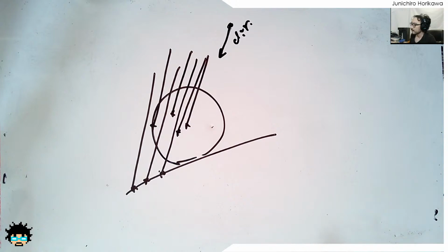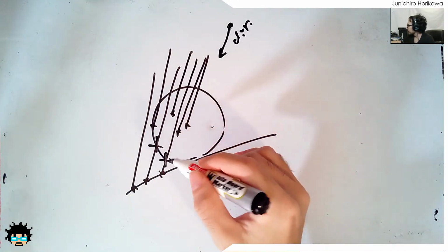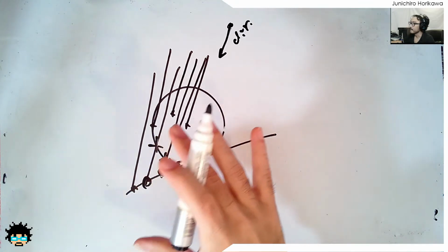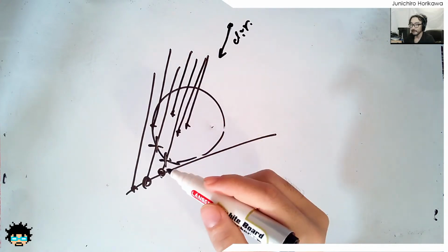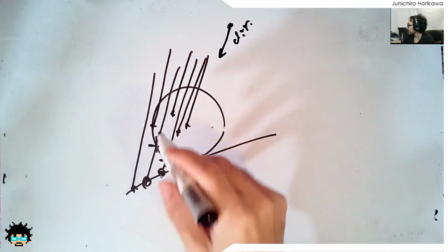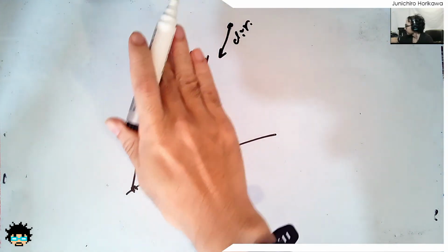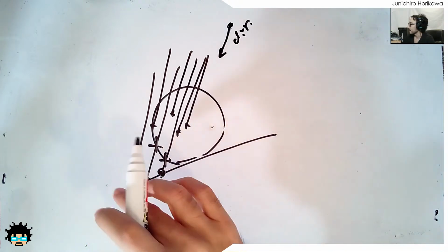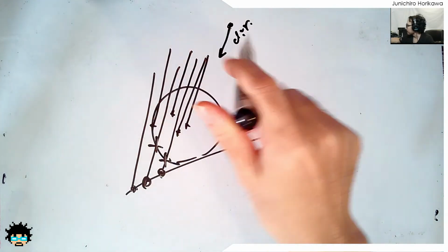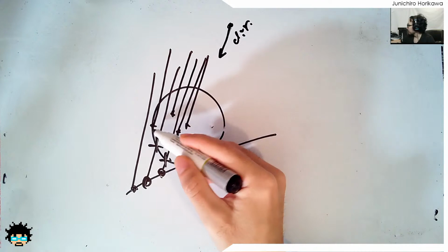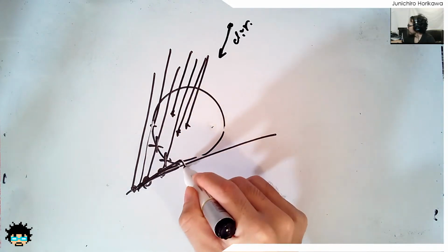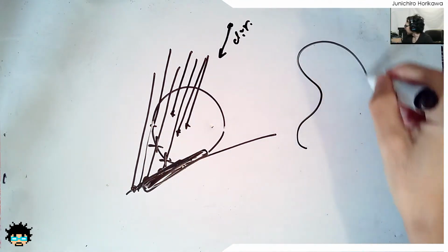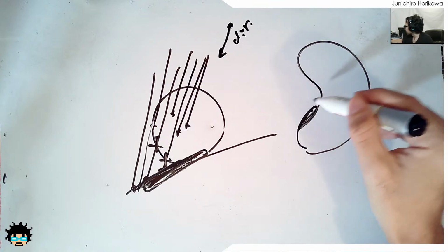And then as soon as you find any intersections on other geometries from this point, then that means this point should be covered by a shadow, right? But this one is not covered by a geometry. It doesn't hit with any geometry, so this doesn't have any hit. So that means it is not covered by a shadow. You can see through with this sun direction. So by doing it, you'll be able to define these places on the floor as shadows, and if you have a self-intersect or self shadows, like these places should be shadowed as well.